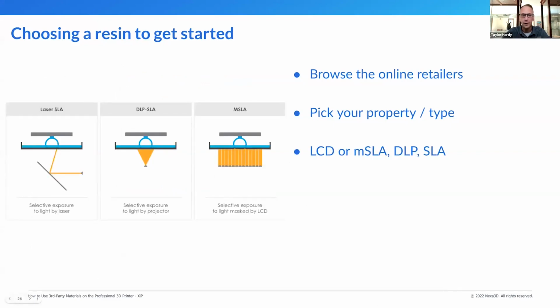So of course you want to make sure you're picking the right type of resin. Some are listed strictly as DLP, some are more for LCD, SLA, some are both. And then of course you also see some that are specifically advertised for MSLA, which is kind of what I prefer to go with, something that is going to 100% work with the machine that I'm using. So you always want to be cognizant of what resin you're buying, because there are a lot of options out there.